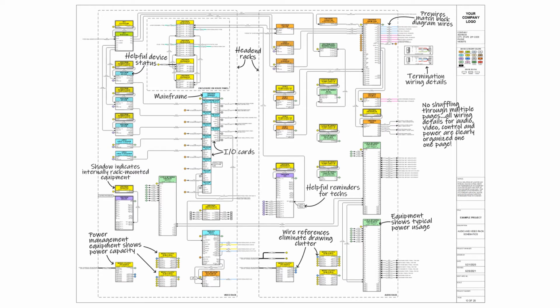So, these engineering drawings are the point-to-point wiring schematics for the AV racks, theater racks, and any head ends in room electronics. They're detailed drawings that show much more than can be shown on the previous block diagram. They're created with the help of the block diagram and follow the same category color scheme for the device symbols.